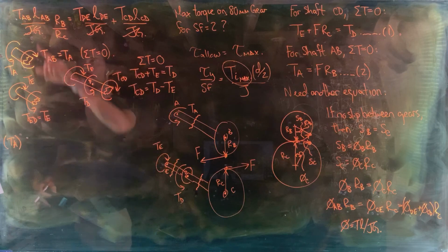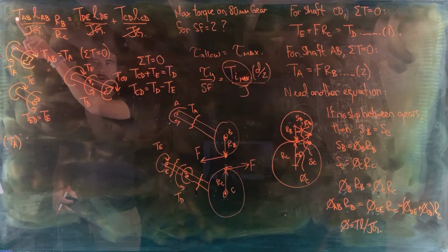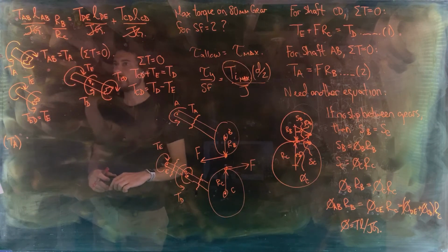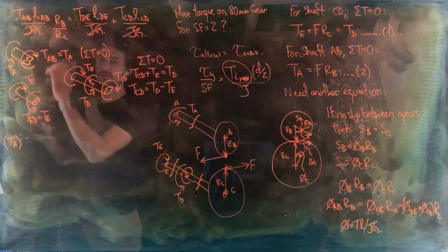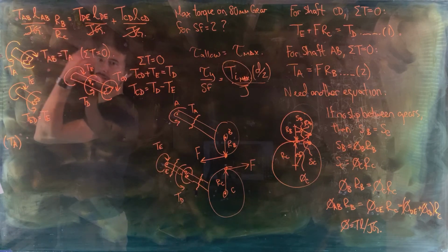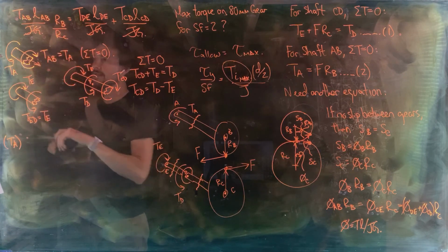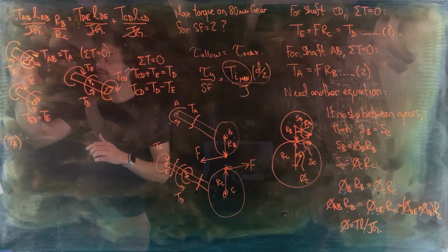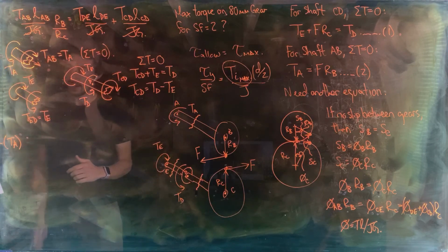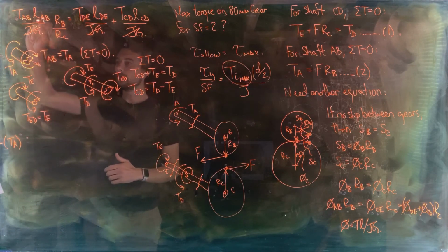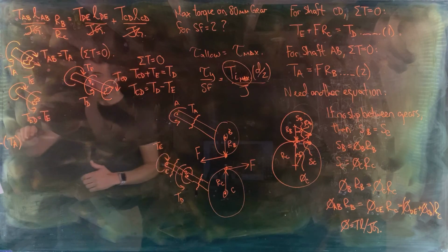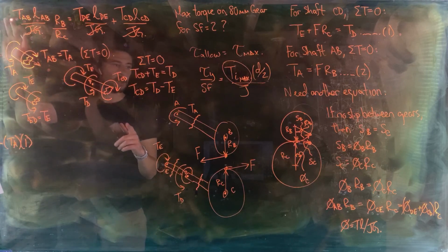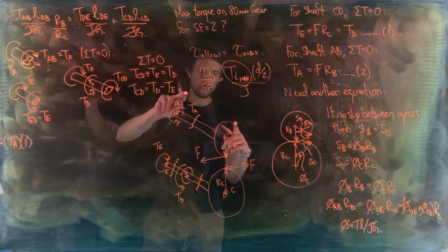But remember, when you put it into the equation for angle of twist and you're using superposition, you need to make sure that you get the signs correct. So here you want to use your right-hand rule with your thumb pointing outwards from the section cut. That's in this direction. Fingers curl in the direction of a positive internal torque. They're curling in the opposite direction of TA, so this needs to be a negative there. Then we've got the length of segment AB, which was 1 meter. That's gone from the glass now, but up earlier you would have seen that this whole length here was 1 meter.